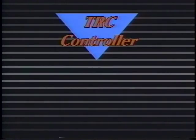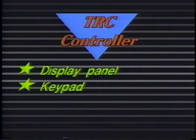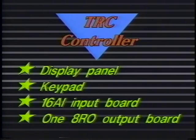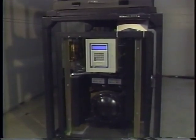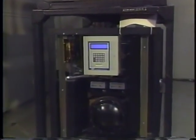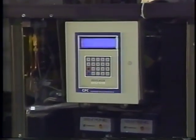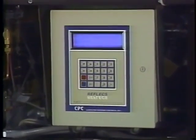The TRC controller consists of a display panel, a keypad, a 16 AI input board, and one 8RO output board. The TRC controller is only used on the RCU5A. The display panel provides information about system compressor status and the controller operation.